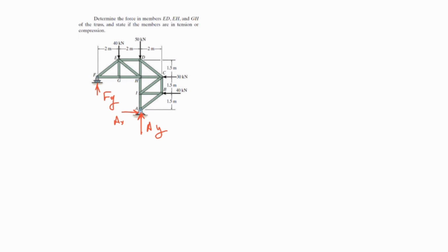And as we said, the free body diagram of the whole system has three equations, and we usually don't care about sigma of x and sigma of y, and we usually don't use them, and the only equation we usually use is sigma m around any point. But here we select A, because by selecting A we get rid of these two unknowns and we can find FY. And by doing that, sigma m around A equal to 0 can be solved.